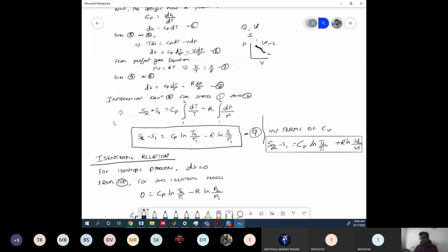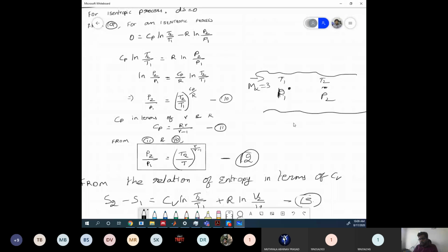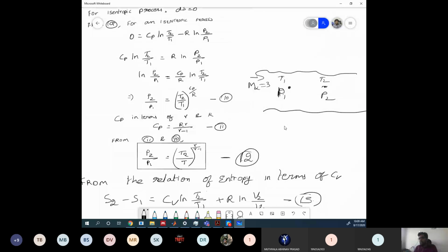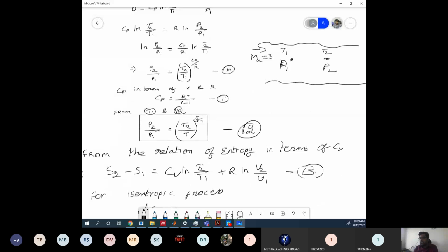From that, we derived how parameters at two different locations in a supersonic field without any disturbance, even though there may be no disturbance, the variables will be related with each other in some way. Here, the specific heat is governing that. So that is what we found out. So we have done this relation.